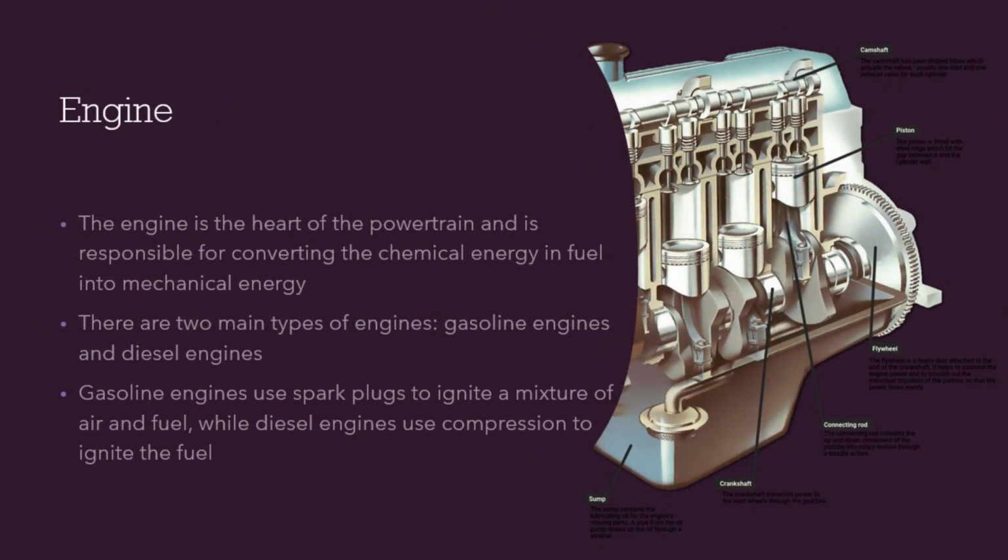Engine. The engine is the heart of the powertrain and is responsible for converting the chemical energy in fuel into mechanical energy. There are two main types of engines: gasoline engines and diesel engines. Gasoline engines use spark plugs to ignite a mixture of air and fuel, while diesel engines use compression to ignite the fuel.